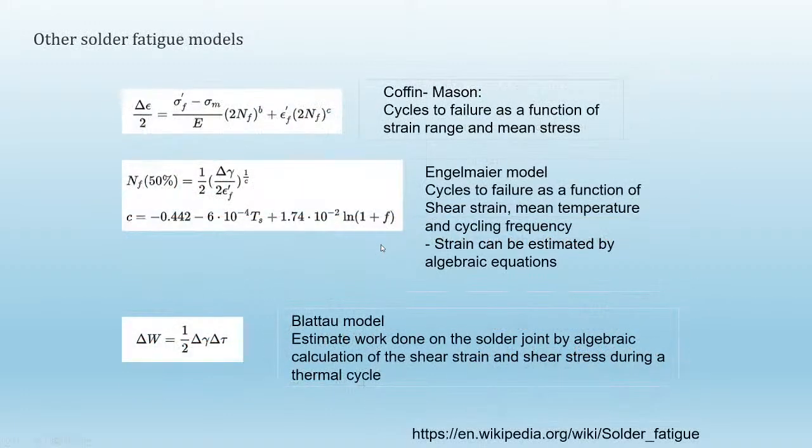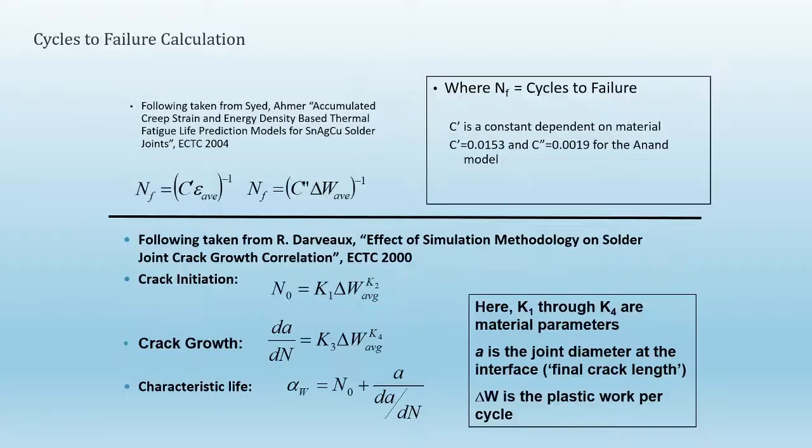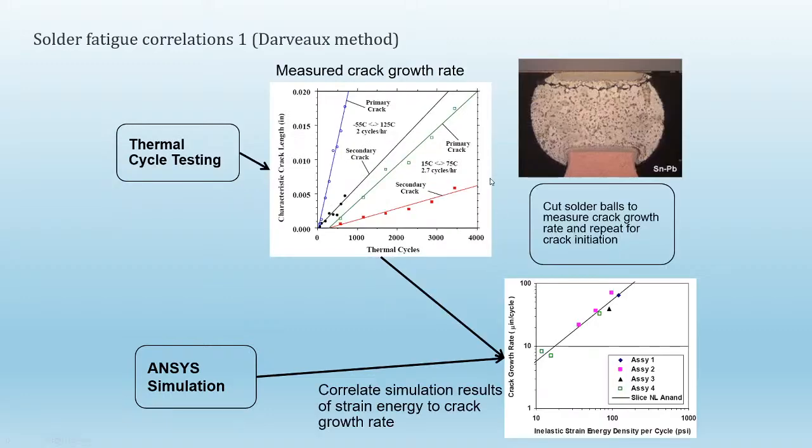If you're buying chips and you want to put them on boards and you want to see, for given conditions, what the impact of a high reliability board or more high reliability solder will be on your system, I would recommend you use tools like Ansys Sherlock and use these types of algebraic equations instead of doing the full simulation of solder balls like here.